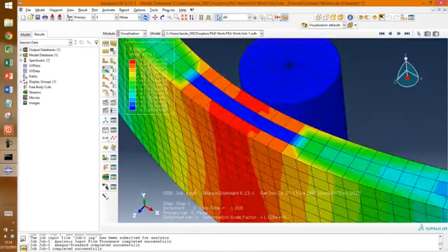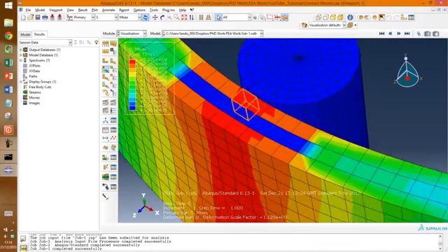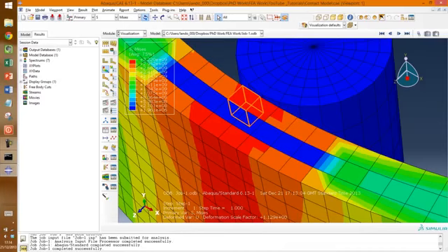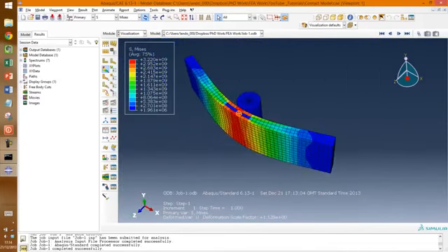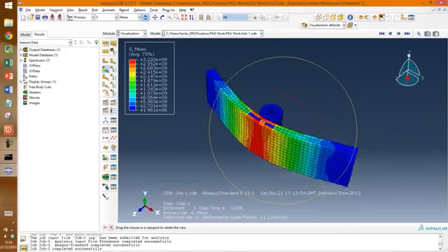And you can see here the high stresses on this side and this side, so that's the compressive stresses on this side and the tensile stresses. There's a very abrupt gradient here between the three elements simply because there aren't enough. We should have more elements there and give us a smoother gradient between the tensile and compressive side. But that's just showing how the contact modeling should work.